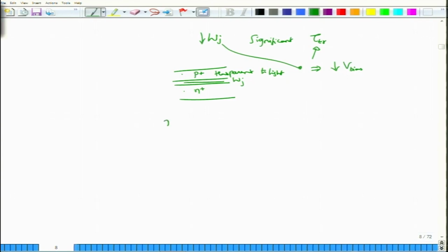Okay. And that is characterized by what is called external quantum efficiency. Quantum efficiency, internal or just the quantum efficiency, is defined as the efficiency with which the electron hole pairs are created for a given photons that are incident. So, when you send photons, how much of these photon, or a single photon if you send, what is the efficiency with which these electron hole pairs are created.